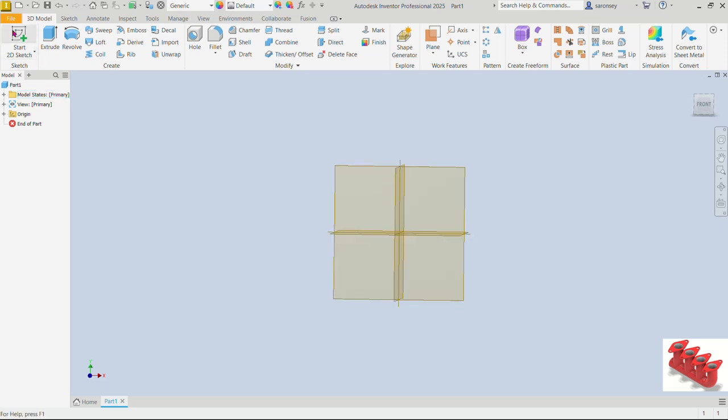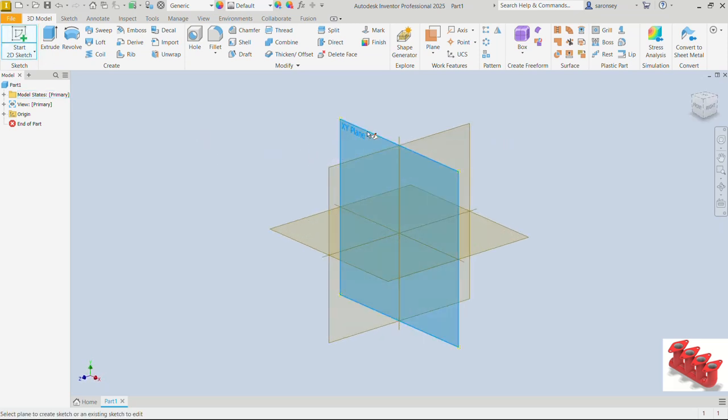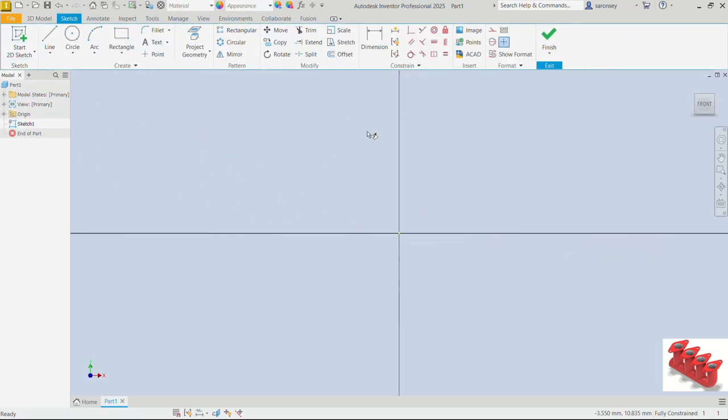We will then pick the 2D sketch command and create the sketch on the XY plane. I mentioned we are creating the path. We will pick the line command. Let's draw this geometry. You can right click and then OK. We want to put a coincident constraint to put the middle of this line at the origin, and we will dimension. The length of this line is going to be 600.